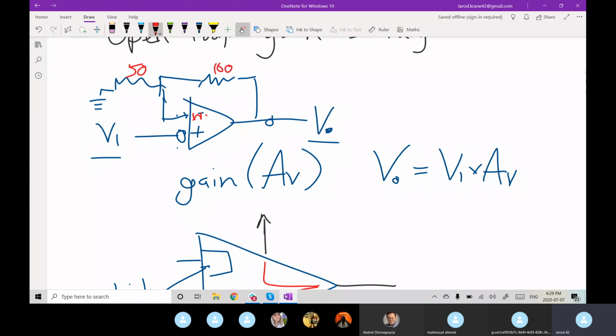So if this also has low impedance, even if it's 100 ohm or sub 100 ohm, the current path is, instead of going through and creating this voltage divider or whatever the system is going to be, the current, because it wants to follow the path of least resistance, would rather go and sink itself into the op-amp.